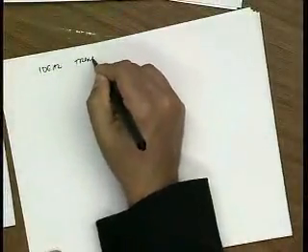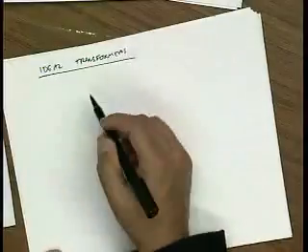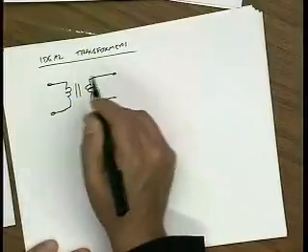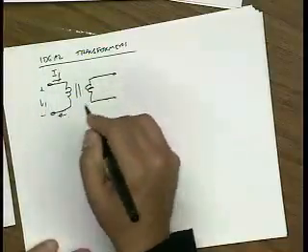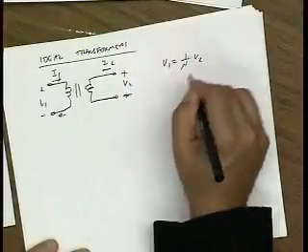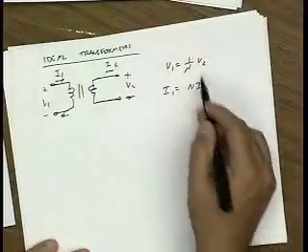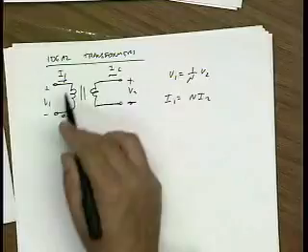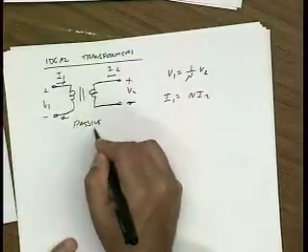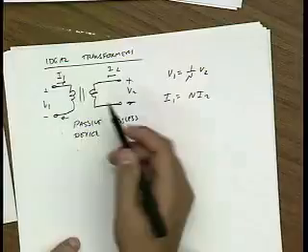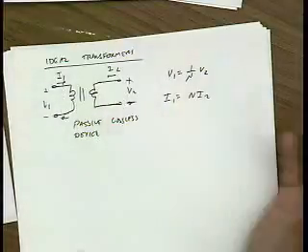Let's also review ideal transformers. For an ideal transformer, the way we draw it is we put these two bars next to these two inductors. Basically the relationship for an ideal transformer is that we get some voltage scaling and some current scaling. By conservation of energy, I just need to tell you that there's voltage scaling, and automatically the current scaling has to look like this. That's because this is a passive, lossless device. So it can't dissipate energy and it can't supply energy. So V1 I1 plus V2 I2 has to equal 0.